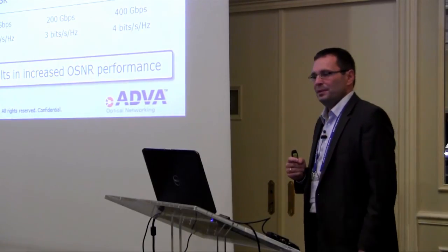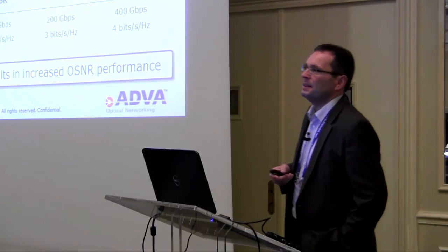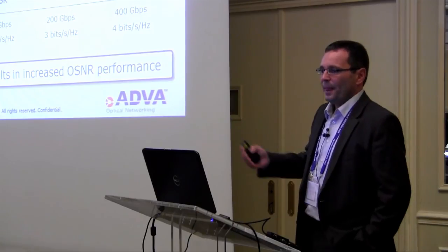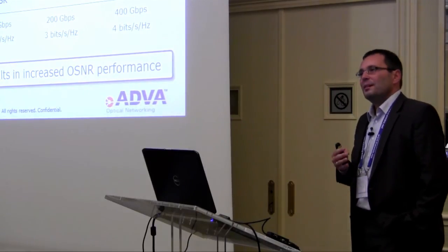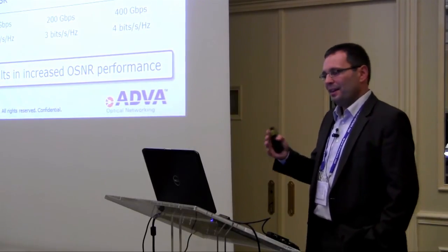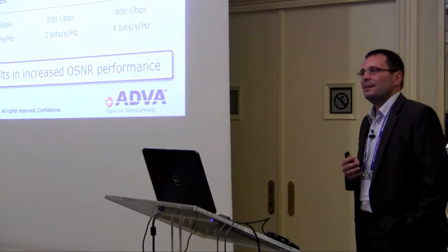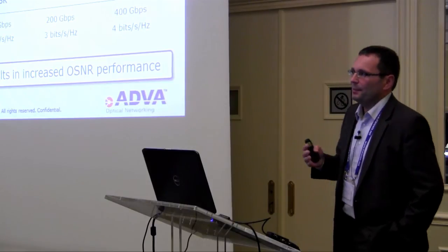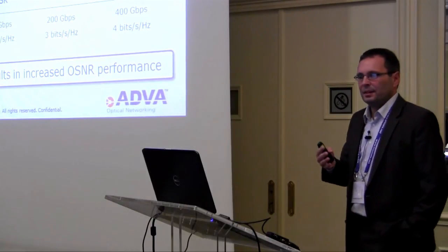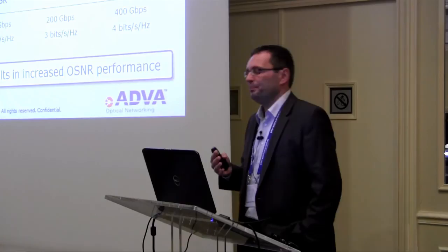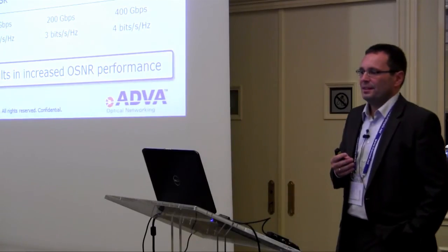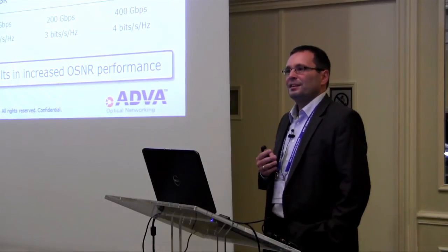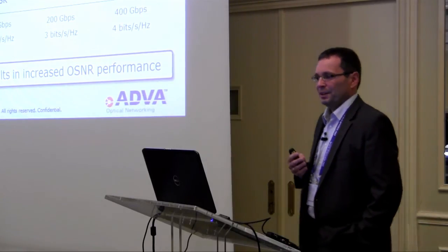And this is why BPSK is used very often in undersea cable, because it can travel longer distances. It's more complex to build, yes, but it gives you either higher capacity, like for 40 gigs, or a much easier way to cope with the dispersion and other effects. And the spectral efficiency, if you use 40 gig in a 50 gigahertz grid, is already higher, 0.8.